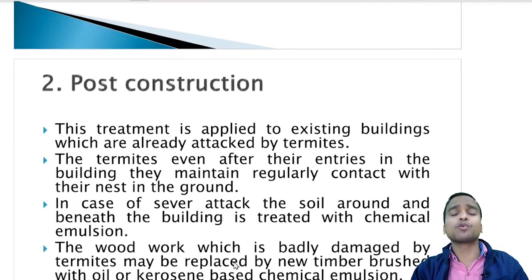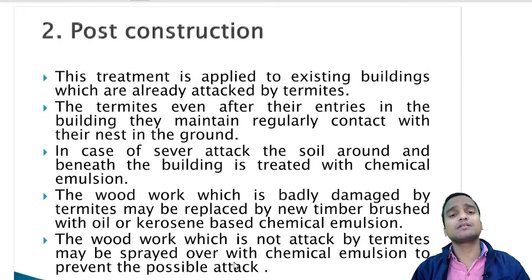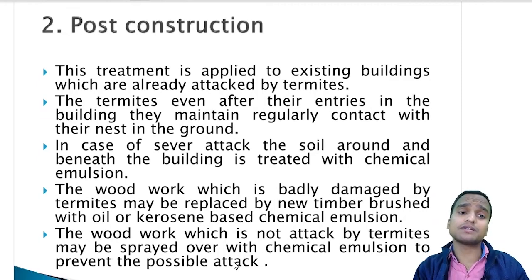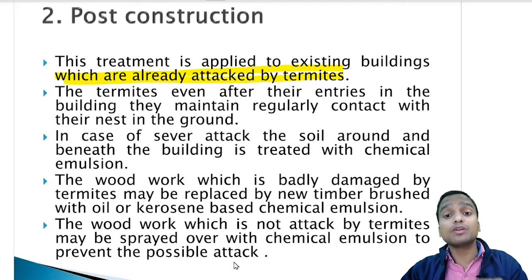Now let us come to the post-construction anti-termite treatment. This treatment is done when the building is already constructed, or as a remedial measure if a building has been infested by termites. So this treatment is applied to existing buildings which are already attacked by termites. And the termites, even after their entry into the building, maintain regular contact with their nest in the ground. That's why destruction of the nest in the ground is more important.